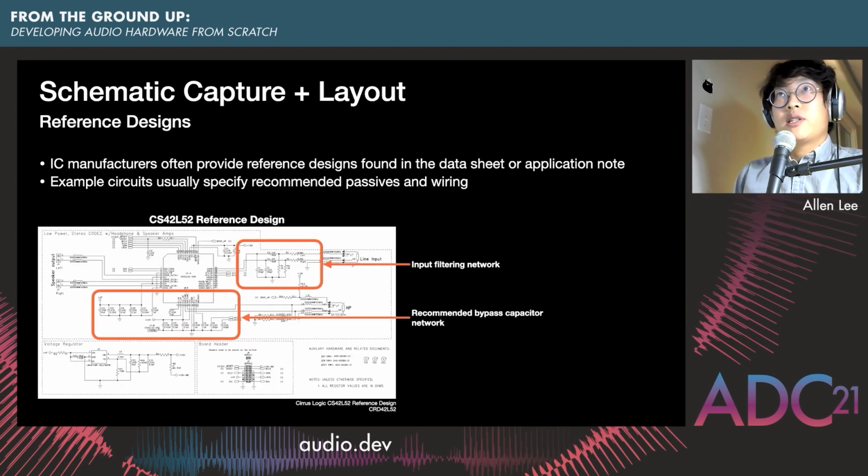Before starting out with the schematic capture and designing your circuits, often a big question that you might ask, especially when dealing with a component that you're not familiar with, is where to start with the design. And so this is where manufacturers' reference designs will come in really handy. Typically, they will supply these reference designs in their data sheet or through a separate application note, and they are a fantastic starting point for your design.